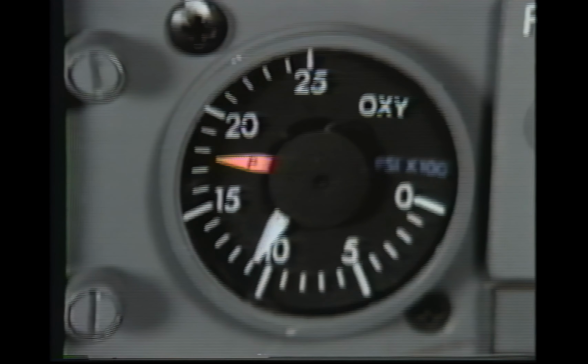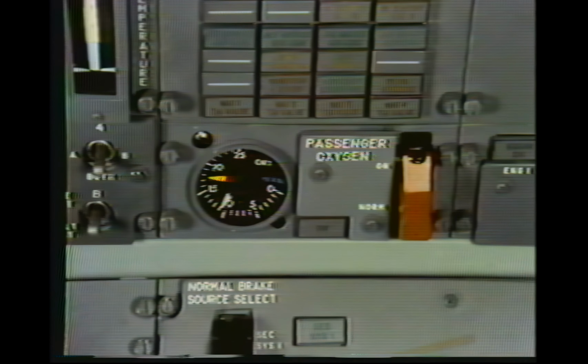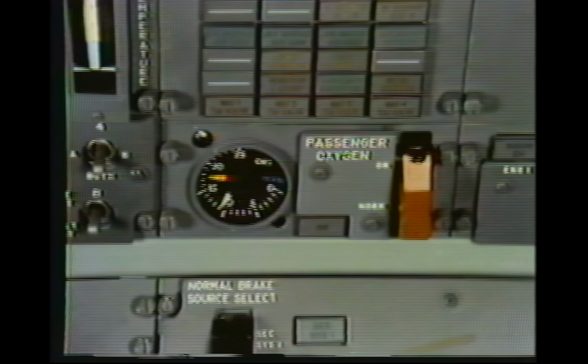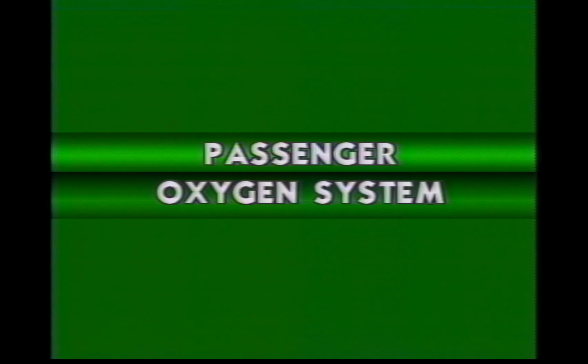The crew and passenger oxygen high pressure gauge is located in the upper right quadrant of the flight engineer's panel. The required pressure for crew and passenger oxygen bottles is listed on this chart on the cockpit door. The crew oxygen on-off valve and low pressure gauge is located on the left wall of the cockpit. The low pressure gauge indicates pressure when the valve is opened. The passenger oxygen system supplies oxygen in the event of a decompression.